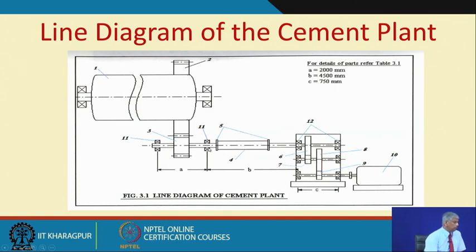And then this is driving a pinion, and then a crown gear or ring gear, which is mounted all along the circumference of the kiln or the drum, and this is supported on bearings. Okay. So, we have some vibration signals taken from the entire plant, and I will show you how sidebands occur in such gearbox signals.